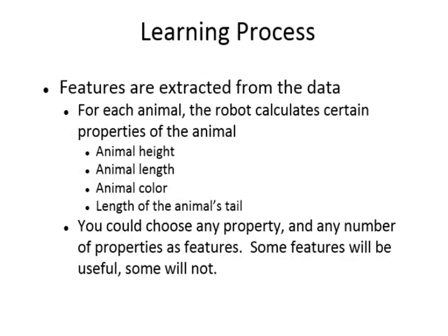The next step of the learning process is to extract features from the data. When we learned about features in machine vision, we looked at features as being only those kinds of things that can be extracted from an image of objects. But features can be many other things as well. They can be things that are extracted from sounds of the objects. Or a feature could be the location where the object was seen. A feature can be any property that helps the robot to distinguish between one thing and another thing.